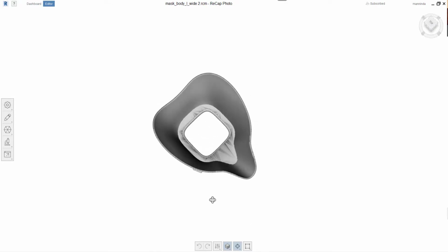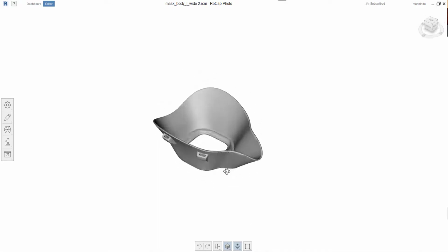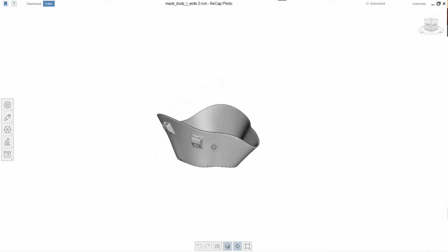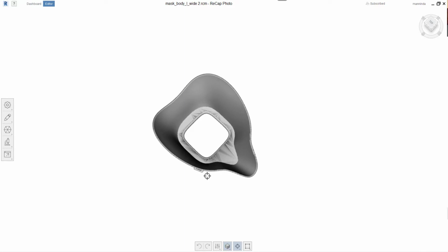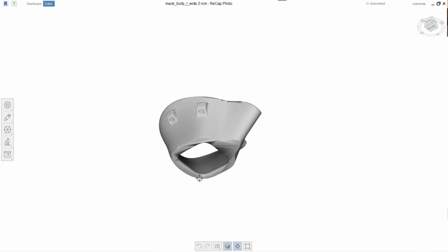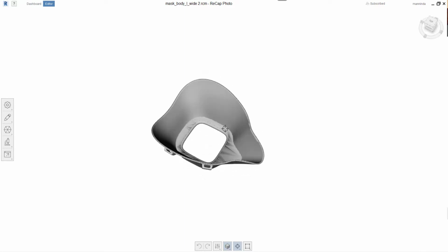And you'll see in here, now we have the mask that was shared on Thingiverse. Now we want to remix this to clean it up a little bit. There's two things I want to do here. I want to be able to deal with the main mask body, and I also want to have this flat section. Now it's flat on the bottom for printing, flat to the print bed, and flat on the top probably because it's mostly convenient, but it also doesn't need to be anything other than flat. I want to slice that off so that it is separate, and I make sure I don't muck up this interface between the printed bits that hold the filter that fit in here and any changes that I make.